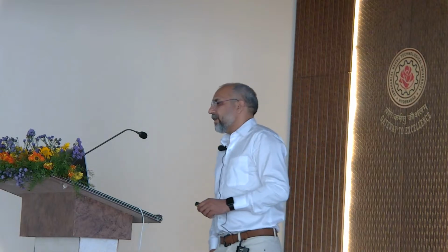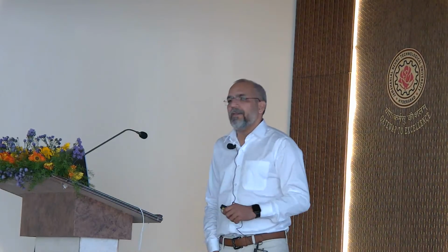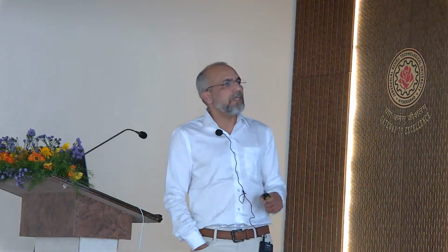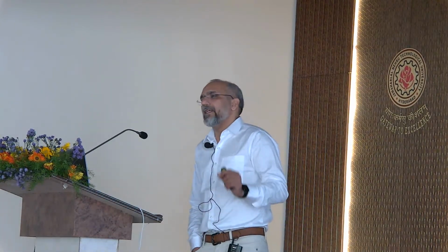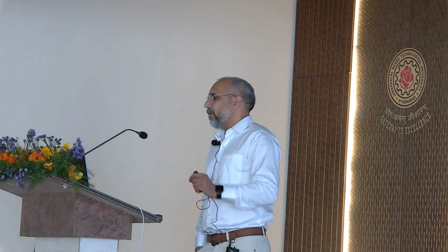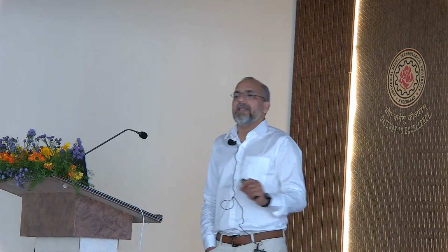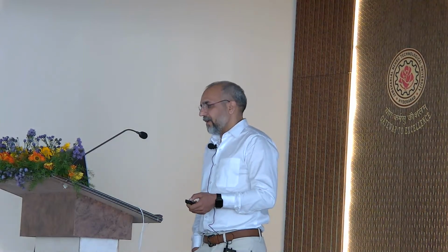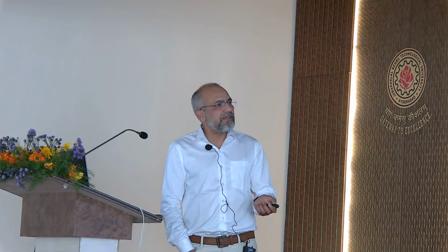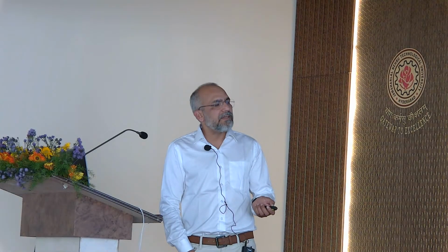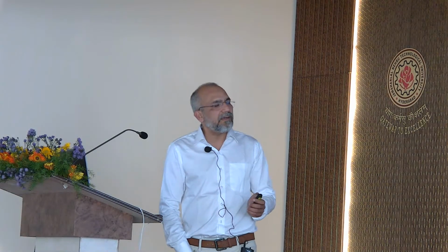The second is liquid phase exfoliation of graphene. Again, here you will use bulk graphite, and then using an exfoliation method, providing energy in the form of vibration, you can break that graphite into graphene layers. And depending on the weight, you can collect different sizes of these graphene layers.